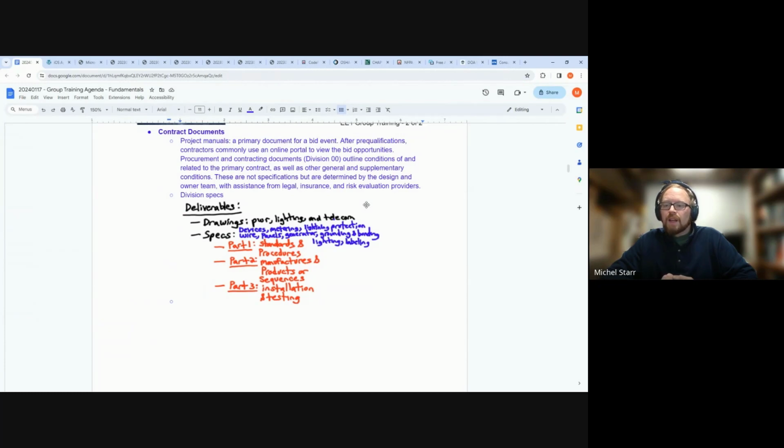necessary term. So you would say a specification section is intended to describe a work result. The work result requires certain standards and even submittals to be given back to the design team to confirm that what the contractor is going to buy and install meets the intent, or otherwise what they put out in the contractor bid and told the owner they were going to install.